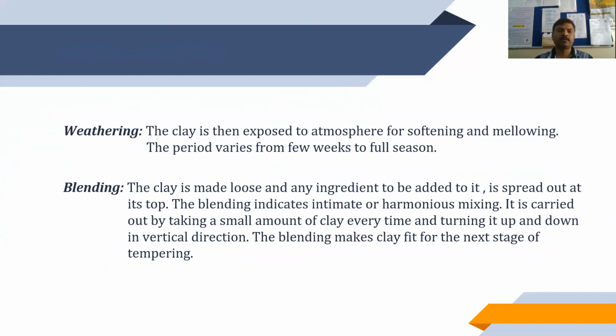The next is the weathering. The clay is exposed to the atmosphere for softening and mellowing. The period varies from a few weeks to a full season. The next one is the blending. The clay is made loose and any ingredients to be added to it are spread out on its top. In blending, we just mix the ingredients present in the soil.